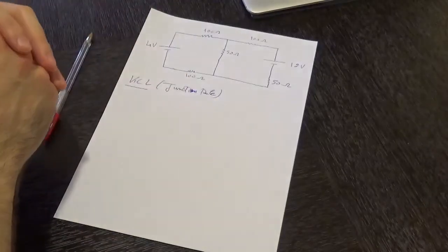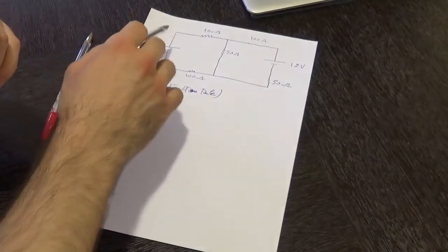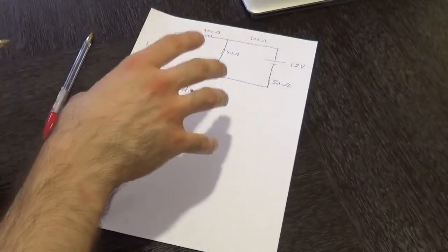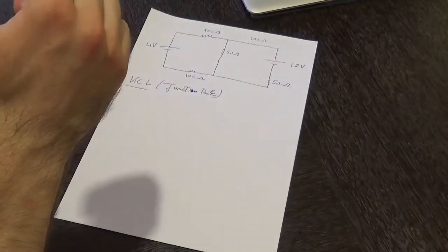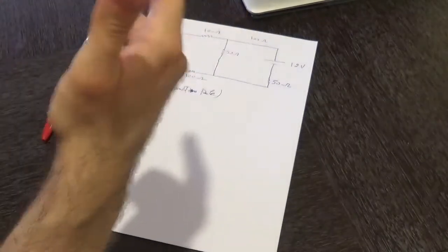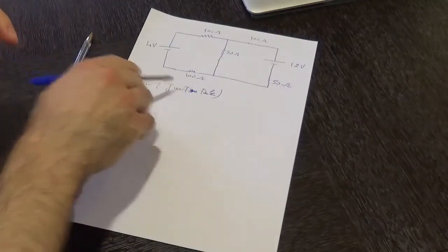Let's have a look at the following circuit, which consists of a bunch of resistors of 150 ohms that are connected to two batteries of 4 and 12 volts. As I have said before, we are going to be applying Kirchhoff current law and Kirchhoff voltage law to that circuit, meaning we are going to be validating the conservation of charges within a circuit and the conservation of energy within an electrical circuit. Starting with KCL, or simply the junction rule.